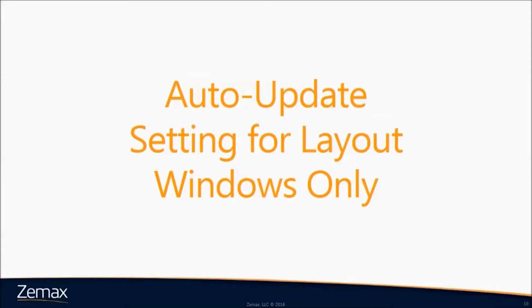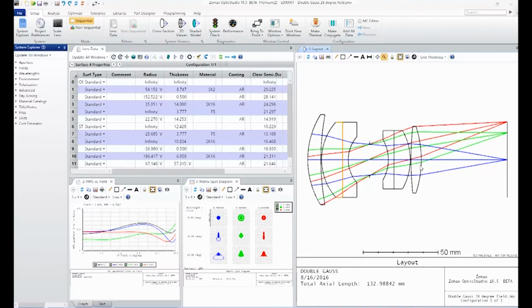Now we're going to show you the new auto update setting for layout windows. Within OpticStudio, users have the ability to see all open analysis windows automatically update whenever changes are made inside of the lens data editor. That can be done by selecting the All Windows option inside of the Auto Update Mode control. However, users may have open analyses which are long running or computationally expensive, for which this control can be